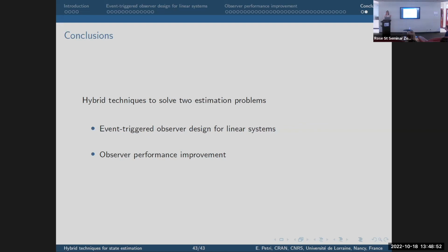All the others, when you have a gain that is different from 0, multiply y minus y hat, so the gain multiplies the measurement noise. So there is always a bound due to the noise. The one with a gain equal to 0 does not amplify the noise because it's not multiplying the noise. And if, thanks to the others, we reset it to have an error that is smaller than the ultimate bound due to the noise of the others, this improves the performance. The error that you obtain at the end is smaller than the others, thanks to the reset, so thanks to the information that the others gave it after some resetting. I hope I was clear.